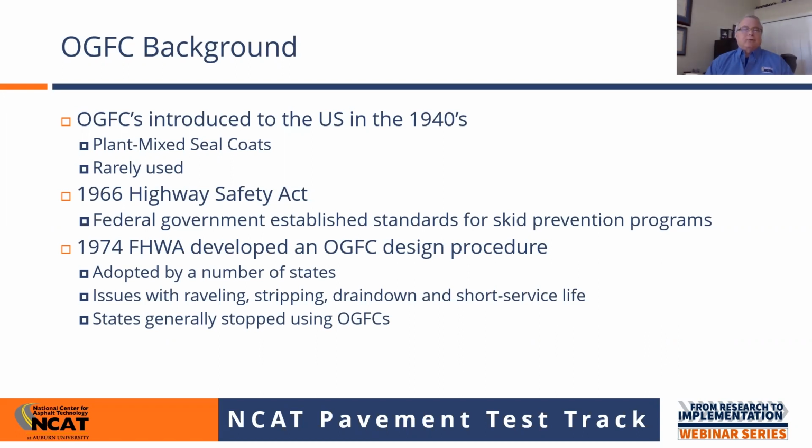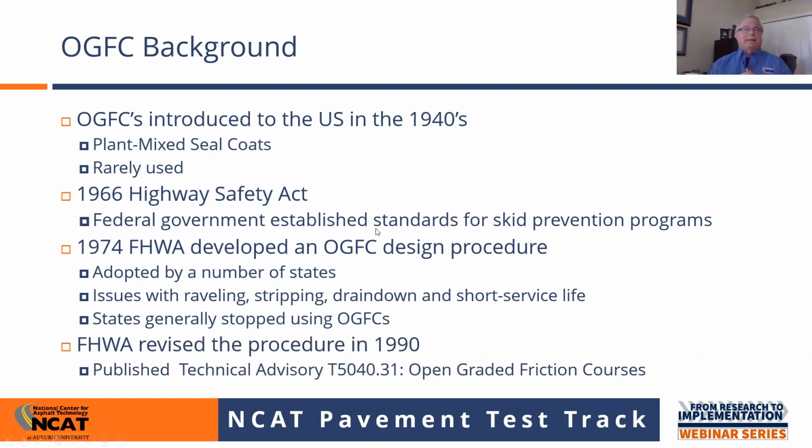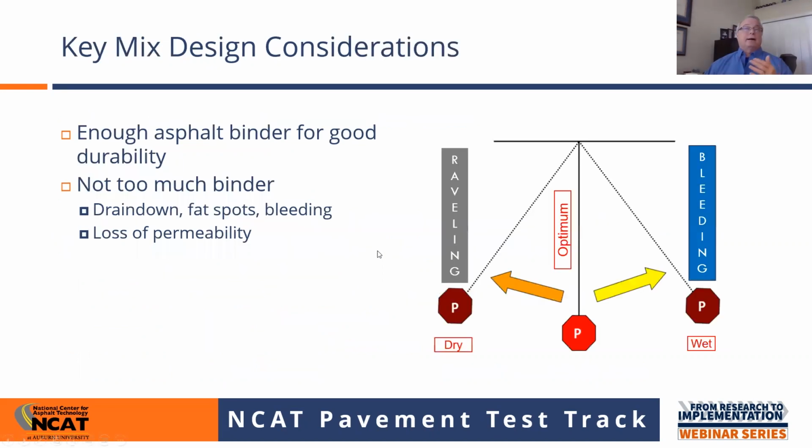So in 1974, the FHWA kind of developed something. It was pretty raw. A number of states used it. Unfortunately, there were problems. They had problems with raveling, stripping, drain down, short service life. I know in some cases, the open graded mixes' aggregate skeleton would kind of collapse and they would have not only a loss of permeability, but they'd have rutting. So they stopped using them. They revised that design procedure in 1990 and published it in a technical advisory. You can see the number. So that was out there for a while.